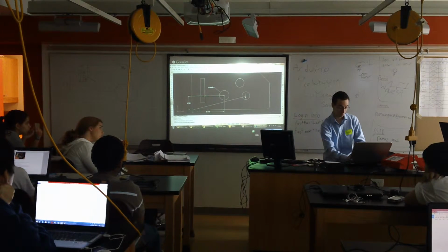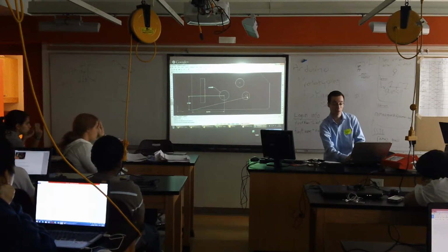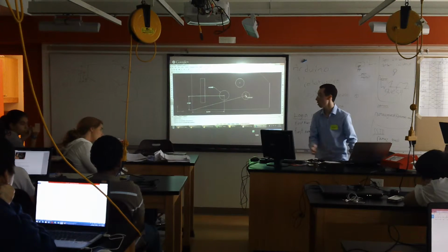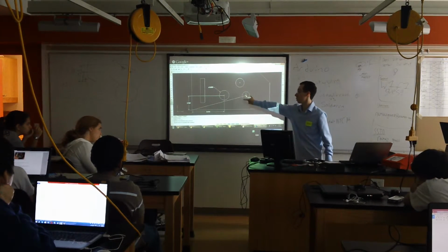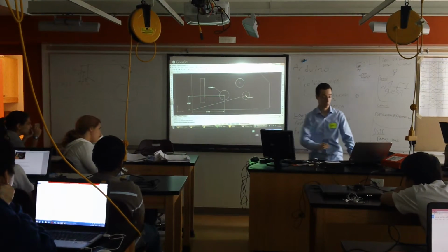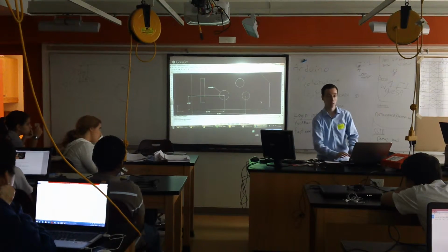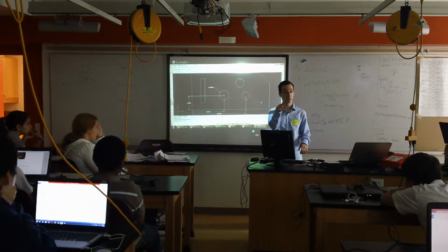Now when I move up here, you'll see the center mark should appear, but it's not. Okay, there we go. See how that center mark appears? When I move close to it, it snaps right onto it. So I know that the computer recognizes I'm trying to dimension this to the circle, because the computer understands the standards here. Awesome, good question. Did that answer it?